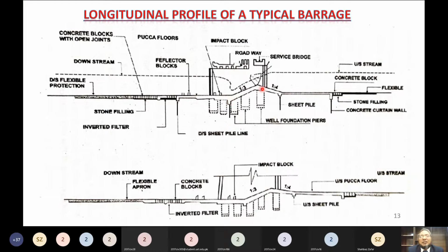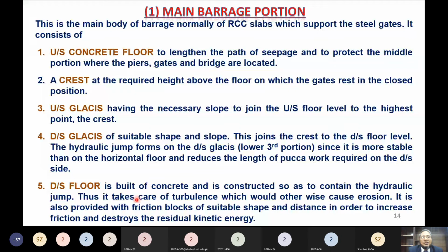And this is very important, downstream glacis, because here we expect the formation of hydraulic jump. Then what is the next? That is the downstream concrete floor. So this is also built of RCC, and it is constructed so as to contain the hydraulic jump.